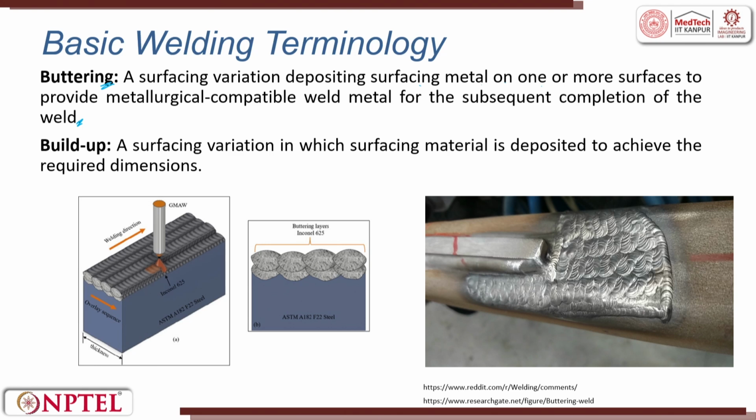If you go back, it is like wetting, right. Then build-up is a surfacing variation in which surfacing metal is deposited to achieve the required dimension. You can see here a buttering layer is formed in Inconel 625.